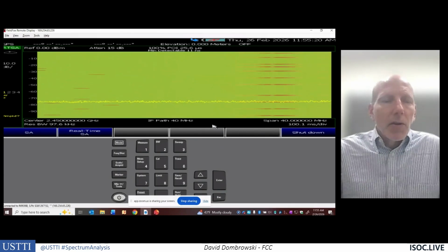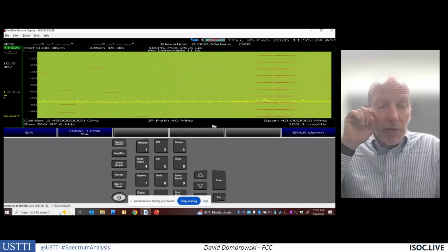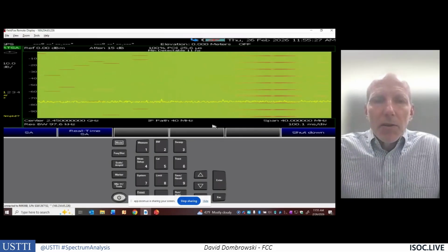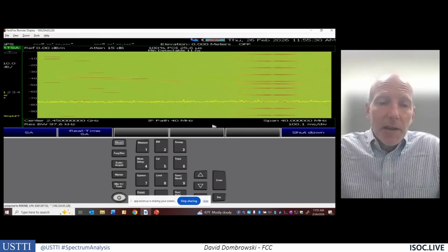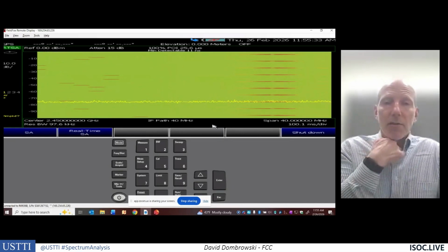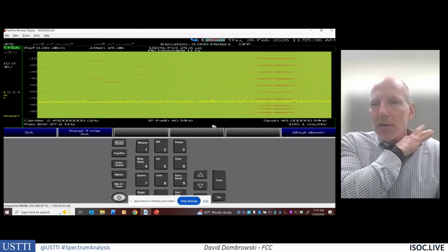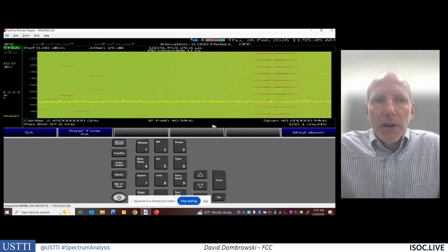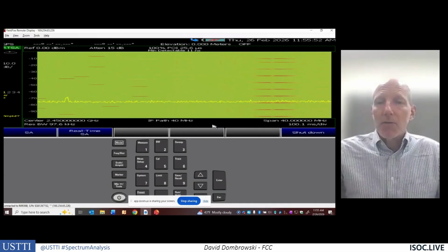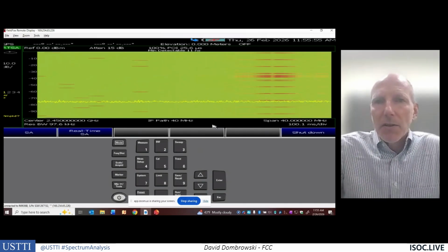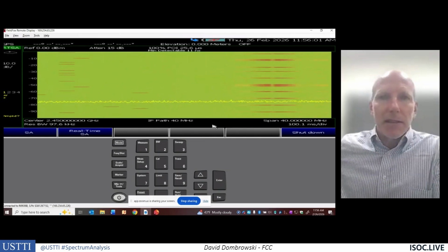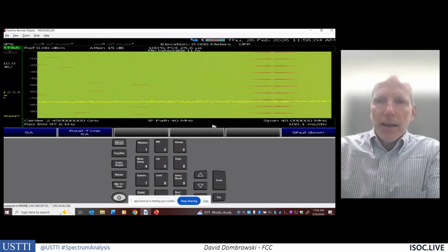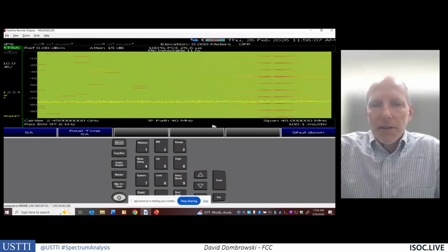And so they call us and ask us to resolve interference issues when they find a source that really increases their noise floor above minus 105 dBm. But sometimes it's not practical. In an urban setting, you may not be able to achieve minus 105 dBm no matter what. So the best way to do that is to maybe sectorize your antennas a little bit better with filtering, maybe use more than 3 sectors. Maybe you're trying to serve a certain area better. You can install a directional antenna so you're not getting the emissions from maybe that LED sign that's down the block. You're pointing the antenna away to better serve that area. Some of the tricks that they can use.